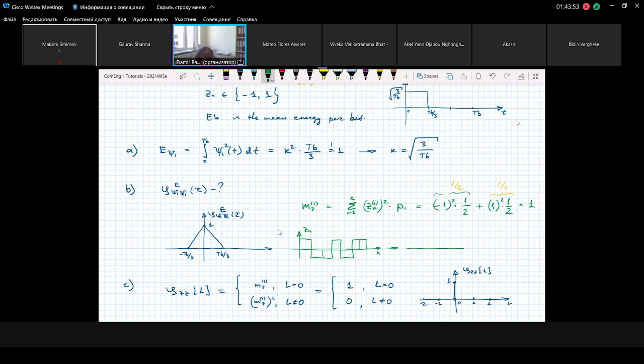Yeah, but what's important is that you have amplitude 1. You calculate the square value, z of n squared. And after you calculate the square value, all of them will have the same amplitude. Because if it had amplitude -1 before, after you calculate the square value, it will be 1. And then the second moment tells you to just calculate the mean value of the squared sequence.